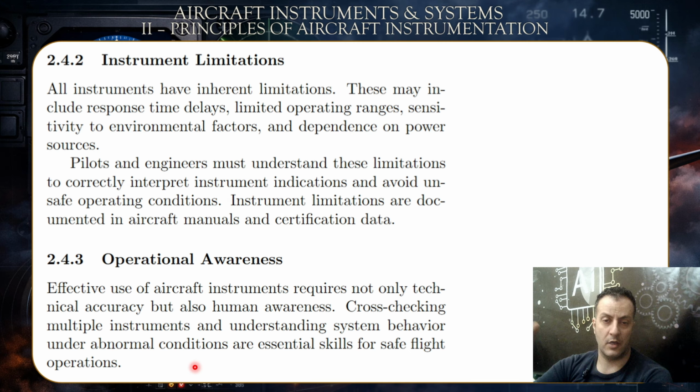To verify that, you need to also check the ASI, because at low speed the aircraft would no longer be climbing. It can enter a stall, which will degrade its lifting capabilities, and that's when you need to correct it, before even the sounding of the stick shaker. That would be the alarm that it's about to happen.